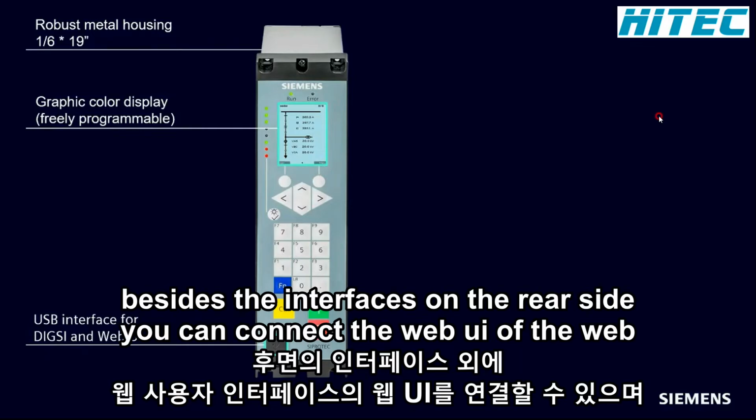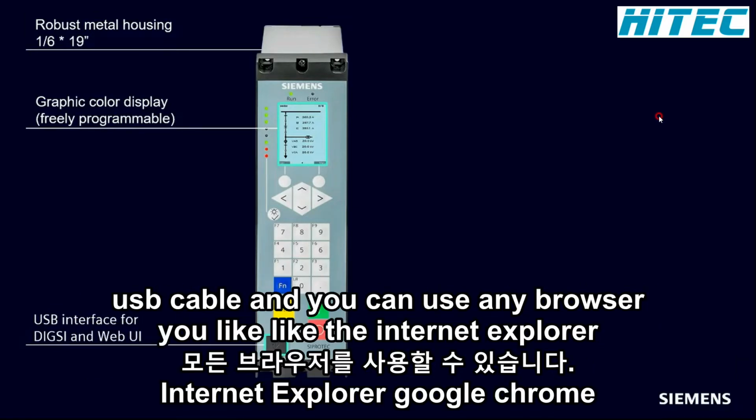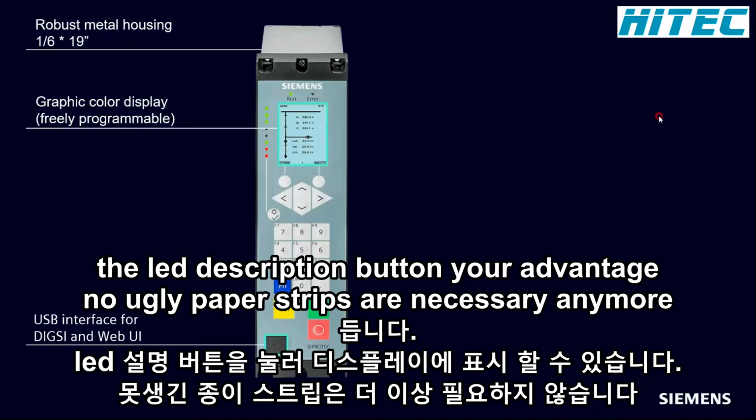Besides the interfaces on the rear side, you can connect the web UI, or the web user interface, and or DIGSI also via USB front port. And this can be done via standard USB cable. And you can use any browser you like, the Internet Explorer, Google Chrome, or Firefox. The LED labels can be shown on the display by pressing the LED description button. Your advantage, no ugly paper strips are necessary anymore.